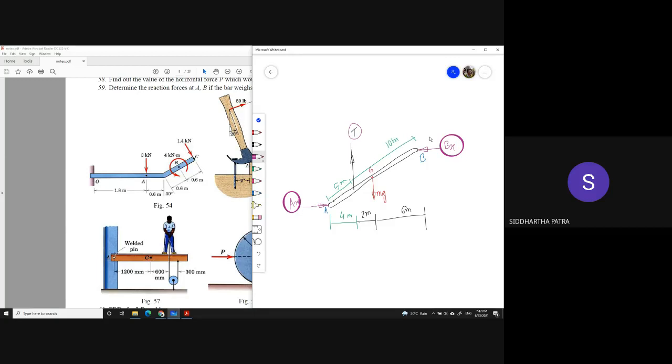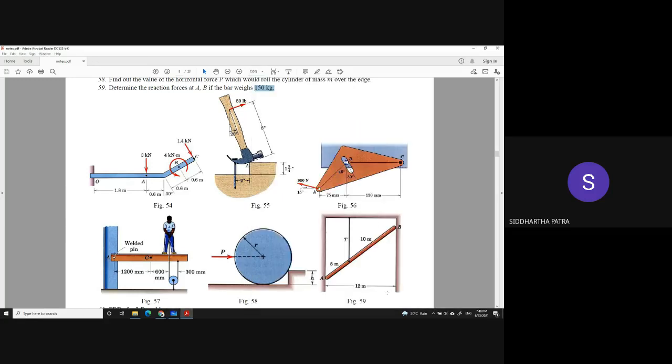Some problems may be a little ambiguous, but there I'll have to make some approximation which is justified. You see, even if there are frictional supports, they have to be through static friction, right? And static coefficients of friction are much smaller compared to 1. So typically friction forces are smaller than the normal forces. And in a situation where I can only accommodate 3 unknowns, I would rather neglect the frictional support. Unless it is specifically mentioned that the surfaces are rough, I can assume them to be pretty smooth and more or less frictionless.